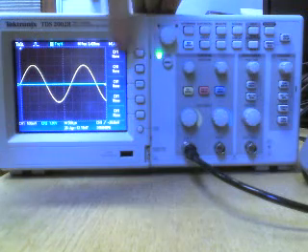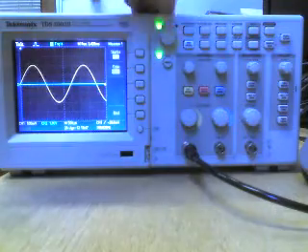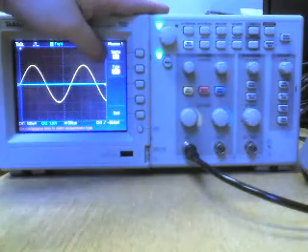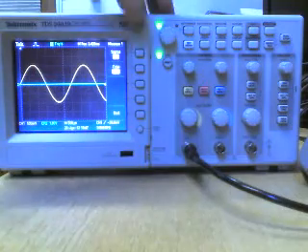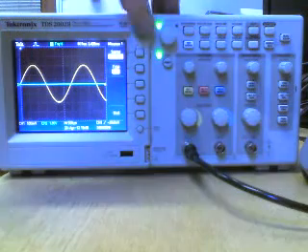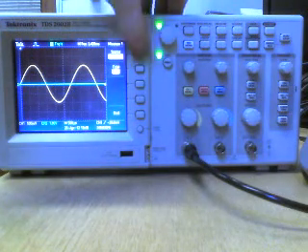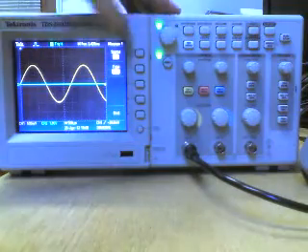So if we want to change it, this one, channel 1, is currently measuring none. Hit the button next to it. You can select the source: channel 1, channel 2, the blue line, math, which is off, this middle one. I'll come to that later on. That's if you want to do any mathematical functions. But at the moment we're on channel 1, so we want to measure channel 1.